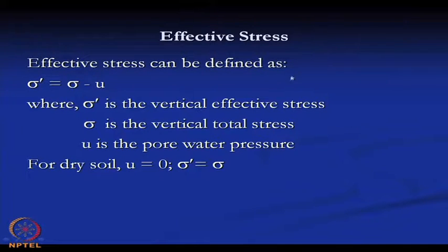So, the next concept is the effective stress concept. Now, what is effective stress? Effective stress can be defined as the total stress minus the pore water pressure. Where sigma dash is the vertical effective stress, sigma is the vertical total stress, and u is the pore water pressure.